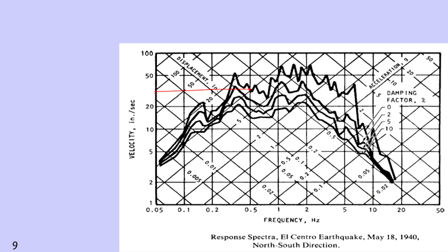And now, how to get displacement from this one? From the same point, you can see on the 45 degrees line here, we can directly drop a line perpendicular to this 45 degrees line. Then you measure displacement. You can see values here: 0.1, 0.2, 0.5, 1, 2, 5 like that. So we can read this is the displacement value.